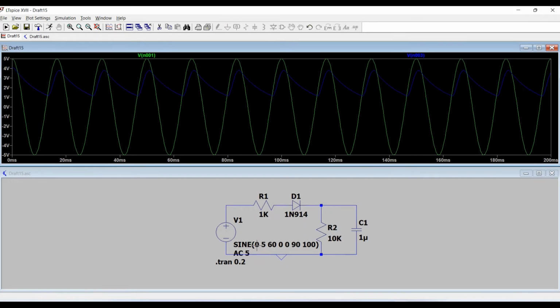See, you are giving a sine function, that is a cosine function because I shifted it by 90 degree of shift. So 90 minus theta, sine of 90 minus theta is cos theta. So like that I'm giving it over here. Then what is happening? First of all, it is in a forward bias. It is charging the capacitor to its peak value, and still due to the presence of the resistor, there is some noise and it cannot charge to exactly 5, but it is nearby, above 4. You can measure it using a cursor as well, and then it retains its value and doesn't drop to 0, and this is how it works.